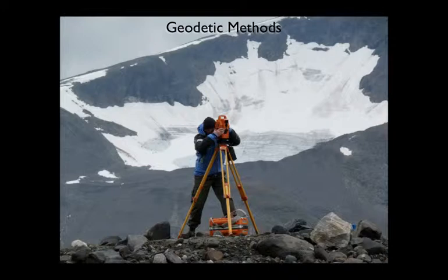Traditionally, aerial photographs have been the main source of data for generating elevation models, but these are quite problematic. The errors have meant that most surveys are separated by at least 10 years. Ground-based surveys, such as with a total station or survey quality GPS, require many hours in the field and can be dangerous. The accuracy of these surveys is usually much greater compared with aerial surveys, but the cost and risks limit their use.